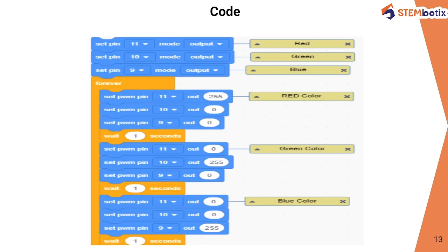The pulse width modulation signal is a practice of modulating the duty cycle of the signal used in the application to control the average power sent to each LED. In the following figure, we see different duty cycles: first 20, then 50%, then 10 and 90, and the duty cycle is going up. So this is how we can control the PWM signal by using the PWM pin on a microcontroller board.